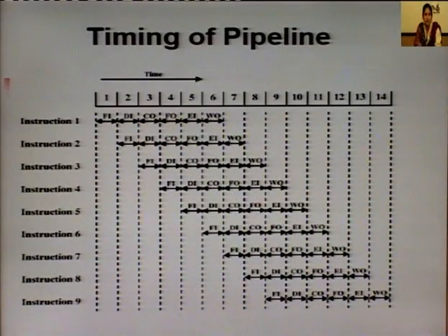So this displays the timing of instruction 1, for example, from clock cycles 1 to 6. The first instruction starts from cycle 1 and completes in the 6th clock cycle, and the second instruction starts from the 2nd clock cycle and completes in the 7th clock cycle simultaneously, and up to the last instruction it is simultaneous processing. That's why it is known as pipelining operations.